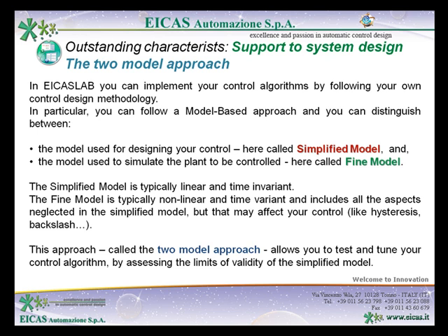Of course, the choice of the simplified and fine model represents a crucial point. A control based on a not appropriate simplified model cannot run correctly, and if your fine model is not accurate enough, it will not be sufficiently representative of reality, and consequently you can obtain good results in simulation, but then on field the control could work differently. On the other side, a fine model too accurate may lead to useless and long computation and simulation time without providing significant results, but with the risk to introduce errors or noise.